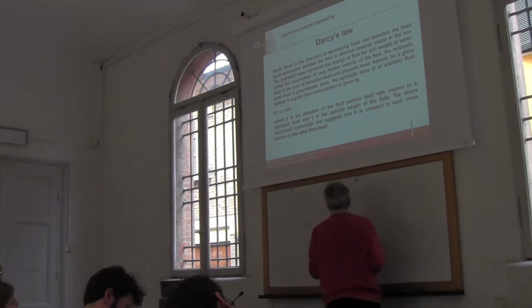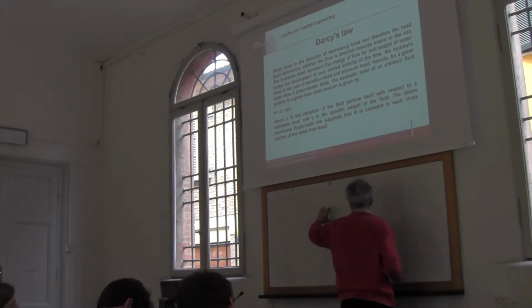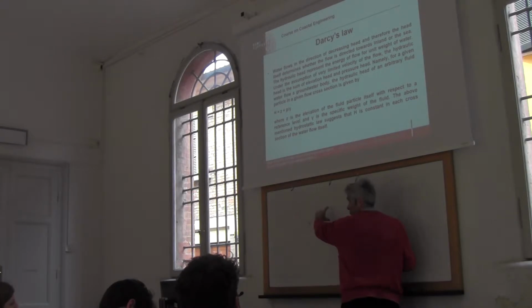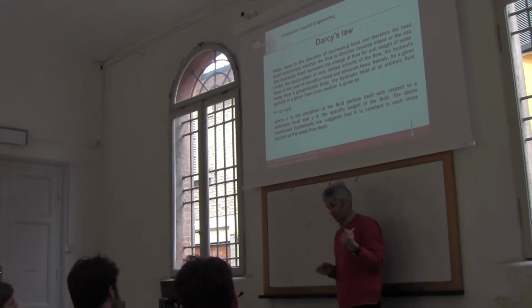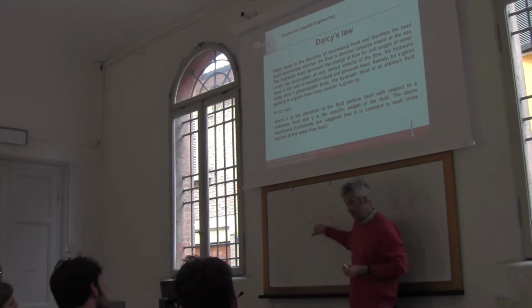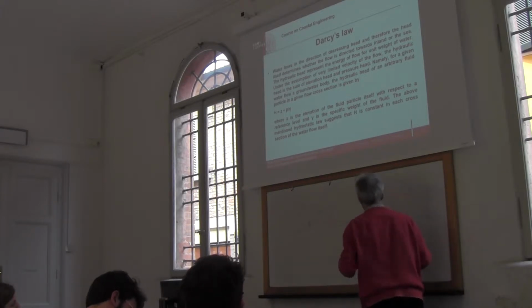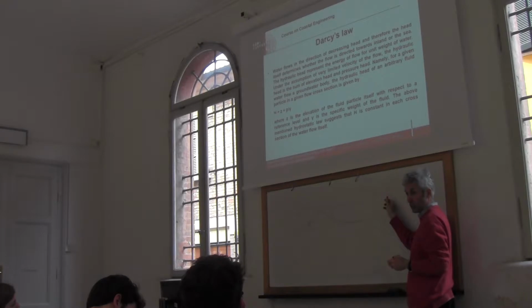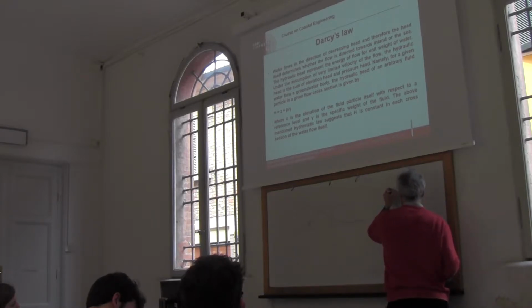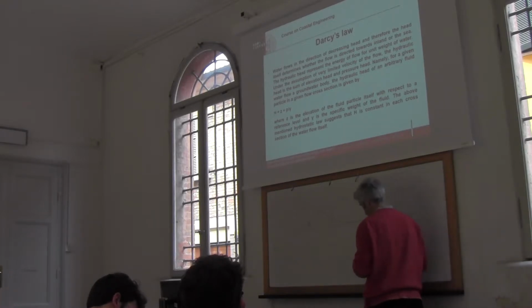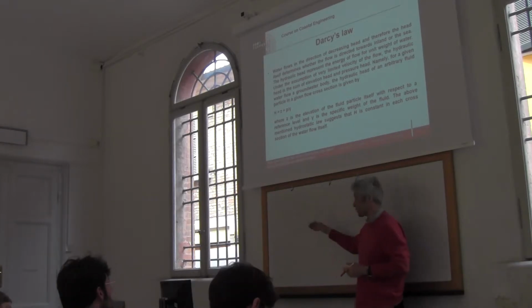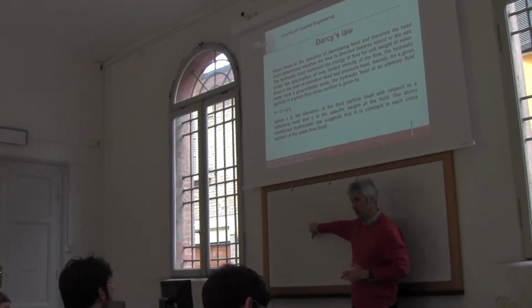Okay, I know that the pressure given by this column of water, salt water, on this point, under the assumption that I have a very reduced velocity here, it can be computed in this way. P is equal to, let me call it gamma S, S stands for salt, times H. It is the depth of the water column above the particle.